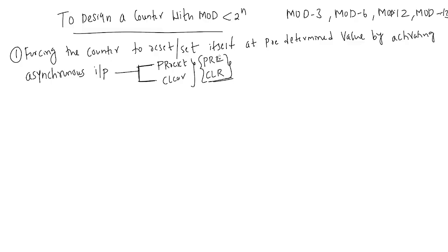Asynchronous inputs work irrespective of the input and clock. Preset will force the output to one. Clear, irrespective of input and clock, will force the output to zero.